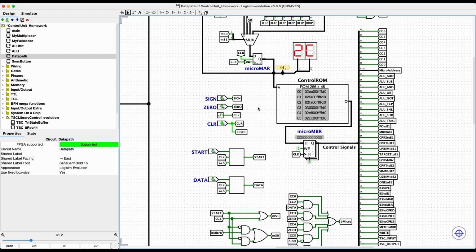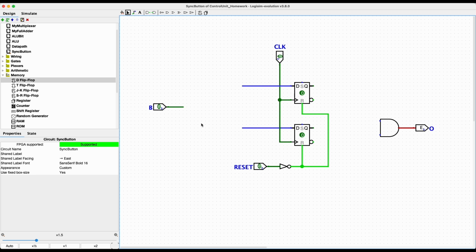So one more thing I want to show you just to make sure you understand how those inputs come together. If you're watching the state machine design video, at the end you put down 2 D flip-flops from memory. You connect this triangle input together, both of them together, and that becomes your clock, the input that you want to be your clock. Now the clear is supposed to reset these to state 0, 0. And this is why I recommend that your first state or the start state start in 0, 0, because when you turn on clear, it'll reset it to state 0, 0.